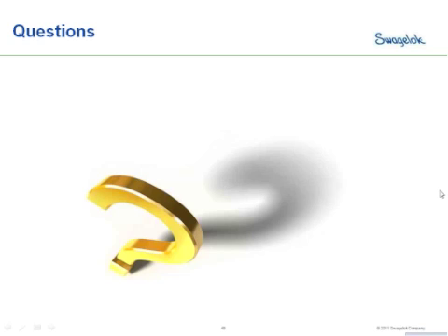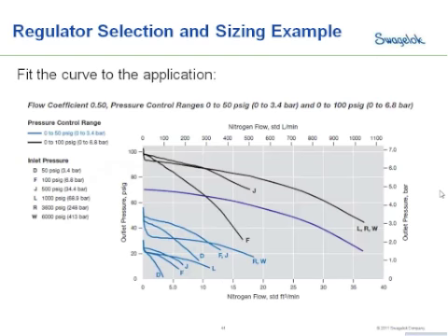One is, can you interpolate below the lowest published flow curve? That's a good question. Let me back up a second. If we just look at this graph, in this case we moved the line vertically down. So we went from that original LR and W black line and slid that line down into that second blue line. And that's sliding up and down the Y scale, which we talked about earlier.